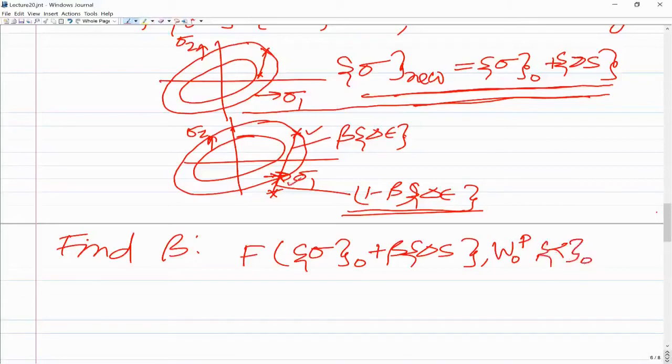also will not change up to this point, because the plastic strains are not changing. So this is equal to 0. So from this, again using Newton-Raphson method, you can find out beta. And once you find beta, then you can calculate the intermediate stress. Intermediate stress, I'm denoting that as sigma dash.